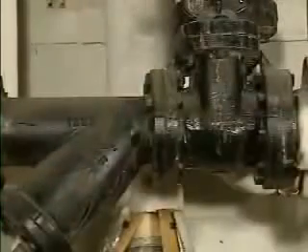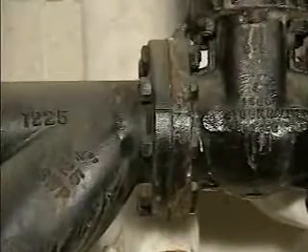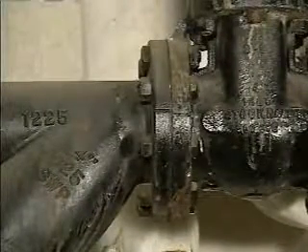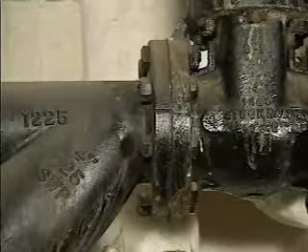For this reason, it is often used in high pressure and high temperature systems, such as hydraulic systems that push and lift heavy loads. Another characteristic of carbon steel is that it's less brittle than other materials, such as stainless steel, so it's able to absorb vibrations. Therefore, it is well suited for systems that generate significant vibrations, such as in vibrators, used to make anodes and aluminum manufacturing processes, lifts, and large gearboxes attached to motors or turbines. Because it is susceptible to corrosion, carbon steel is generally used with non-corrosive gases and liquids.